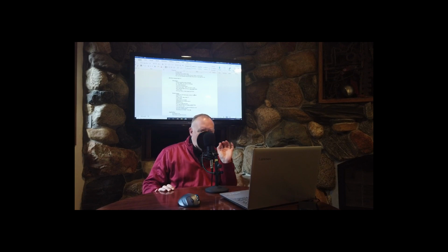All right, ground source heat pumps are usually more efficient than the other refrigeration cycles other than a water-cooled chiller. They are normally more efficient, kW per ton of cooling. They're more efficient than normal split system air conditioners, rooftop units, even air-cooled chillers. They're more efficient than all of those.